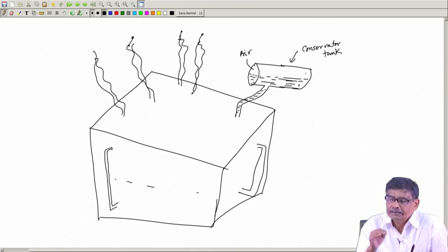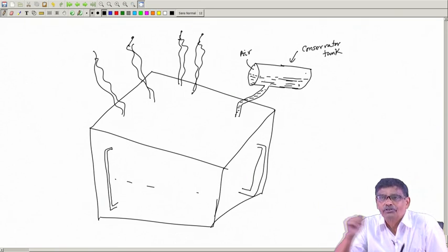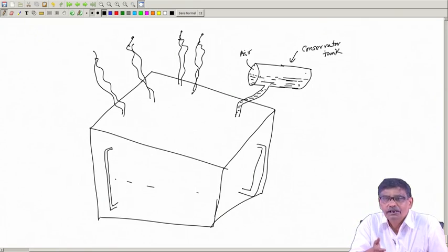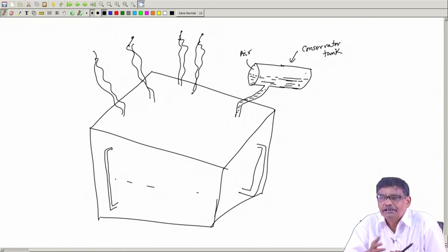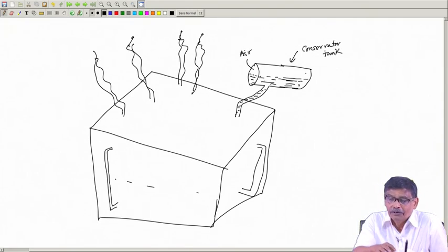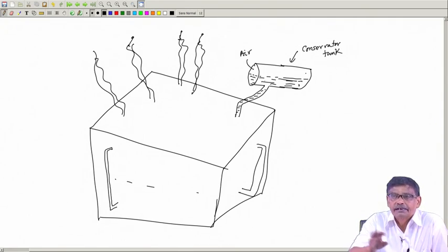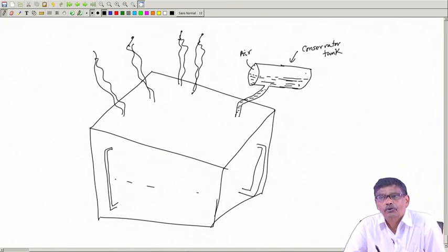Now, you imagine that you have connected load on the transformer. Only core loss was taking place when the transformer was under no load condition. Now, through the secondaries you have connected, it is delivering full load, full kVA. In that case, copper loss comes in.